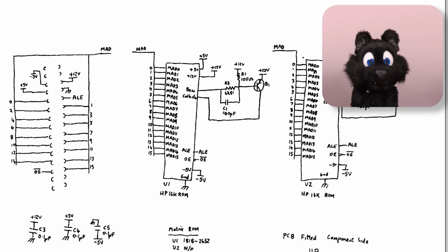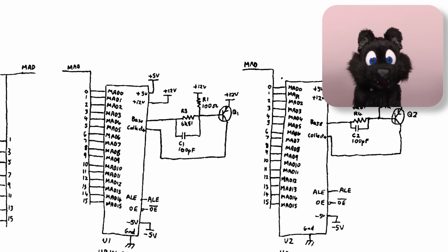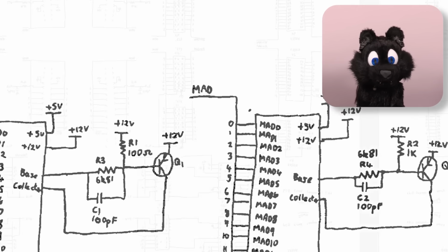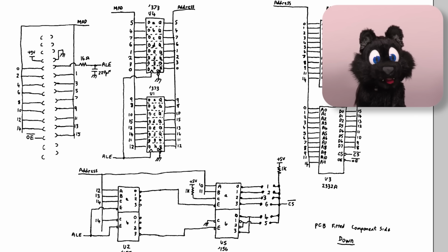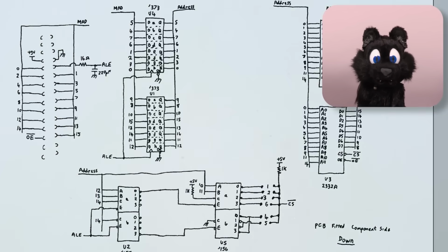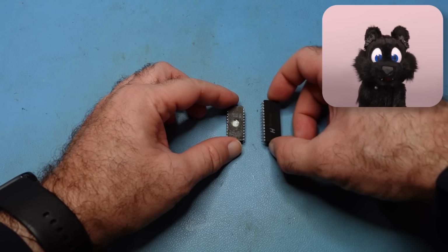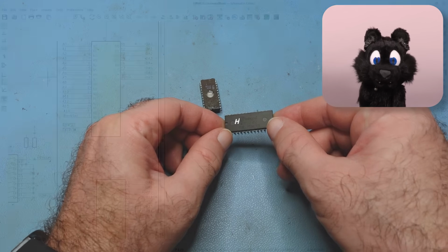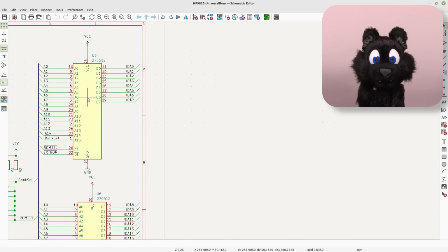Like the RAM, the original way back ROMs had a 12-volt enable line and thus were a bit power hungry. Modern ROMs, both EPROMs and EEPROMs, should be just fine as a replacement. I need some that are larger than 2K or 4K, but still have parallel I/O. The smallest ones I could find here are 64 kilobyte ROMs.